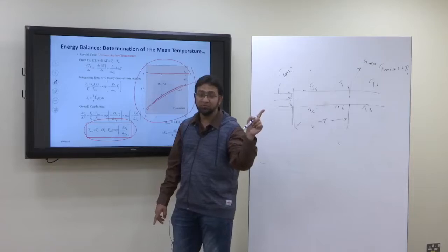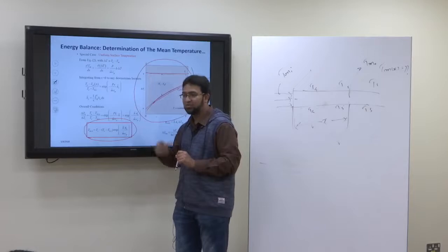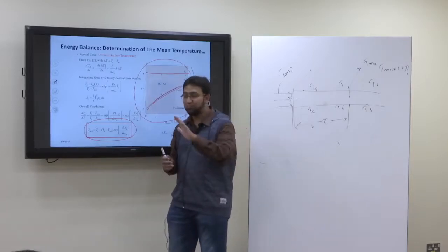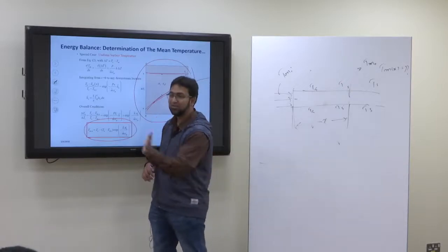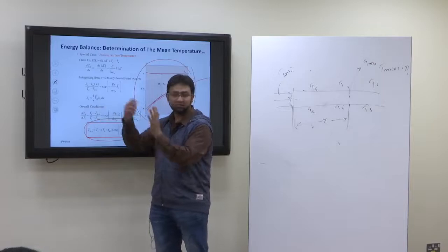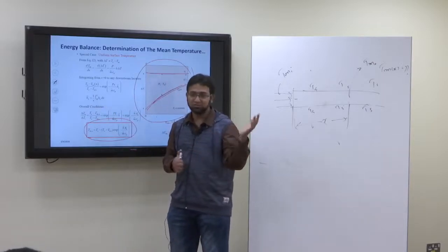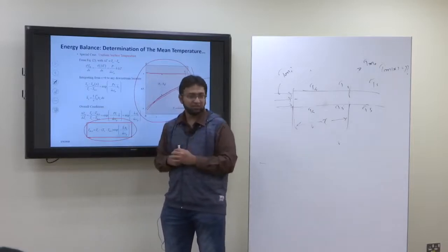Previous formula was for the case of constant heat flux. Again, this formula will be there in the book of formulas. And these formulas are derived by the same concept, that the amount of heat convected is equal to the amount of heat energy rise in the fluid.